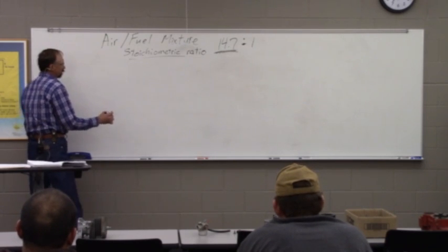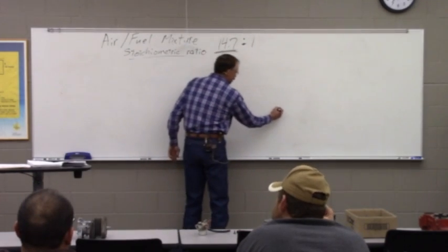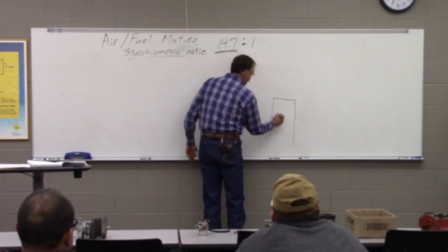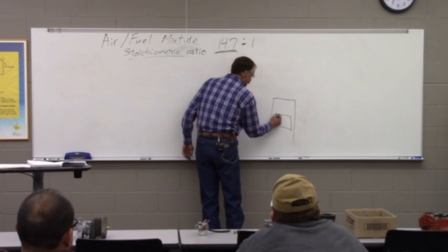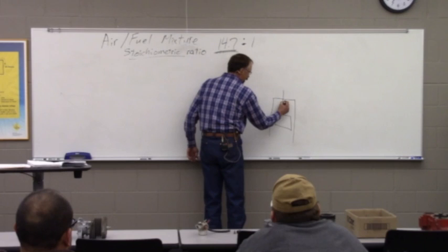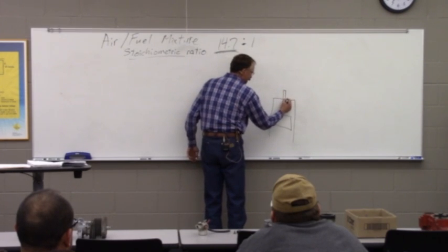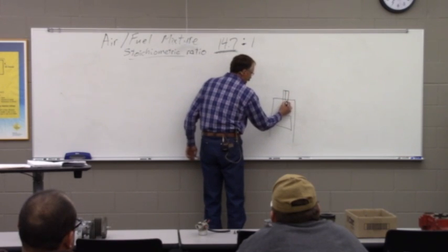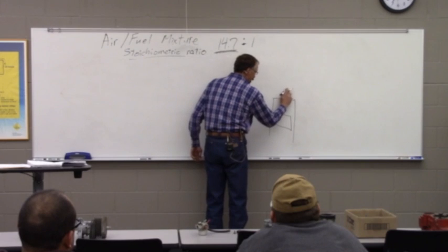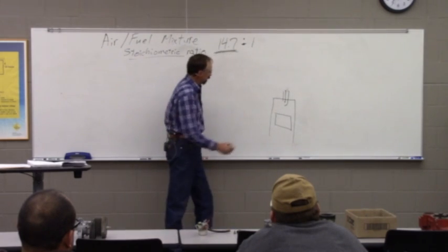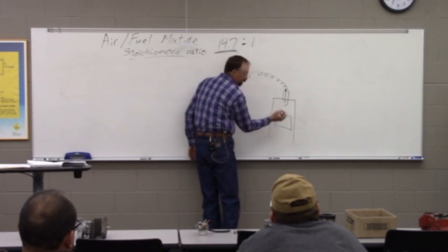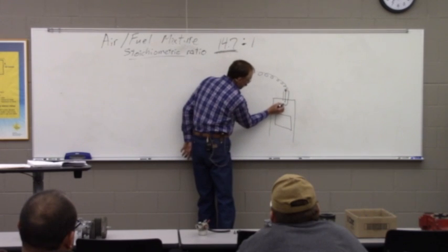So in our gas engines, we're going to do that with a spark plug, which typically we're going to stick right in here in the top of our cylinder. It's going to have a center electrode that's going to be connected to our spark plug wire. And what's actually going to ignite that fuel air mixture is when we jump a spark across this gap in the spark plug.